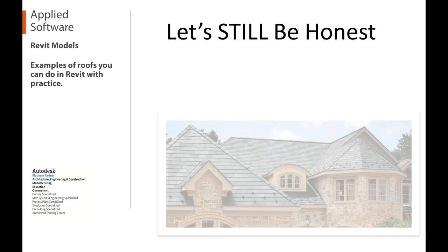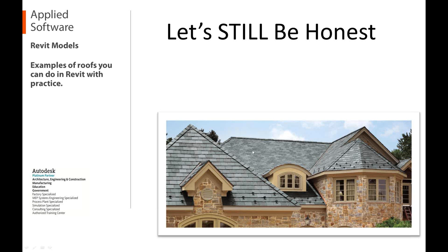This is a really nice shot, I like it. There's a lot going on here. Basically, I can create this roof inside of Revit using some hip roofs. I could use an extrusion, which you might see here. This could be an extrusion, or this could be a gable right here on the left side. Right here with this curved roof, that's definitely an extrusion. That is not a roof by footprint. So we'll take a look at that and I'll show you how to create that inside of Revit.